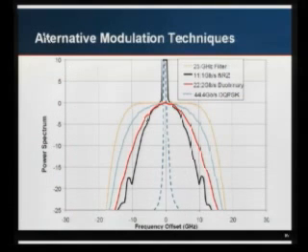Here's a 25 gigahertz filter showing you're encoding more data in the same amount of spectrum, up to 22 gigabits per second in a dual binary. You go all the way up to 44 in a DQPSK. So this is the basis of the technology that makes 40 gig optical work outside of very short reaches. So you can now do long haul 40 gig. All the existing systems out there are using dual binary, DPSK, or something like this.